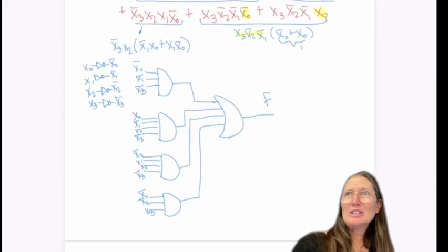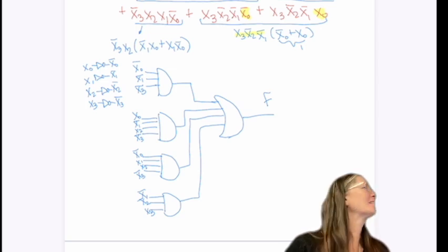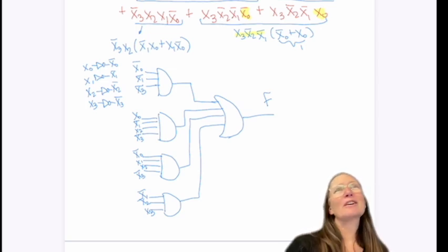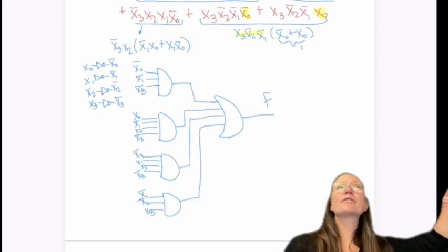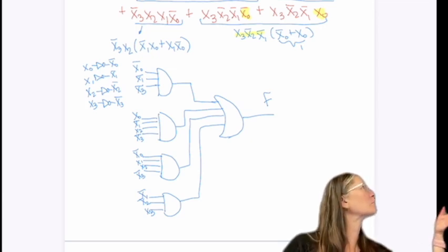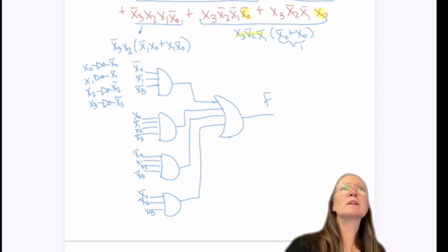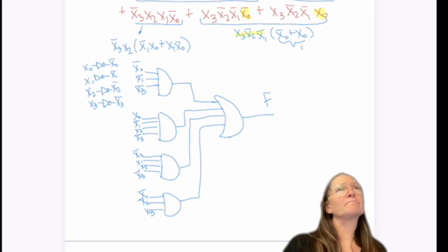Okay, questions? So there's a nice chip out there that does this. If you do want to use a 7-segment LED display, the chip internally has all this logic in it already. So you can just put in the 4 inputs or 3 inputs, however many inputs it has, and then hook it up to a LED display light, and then it will drive it.